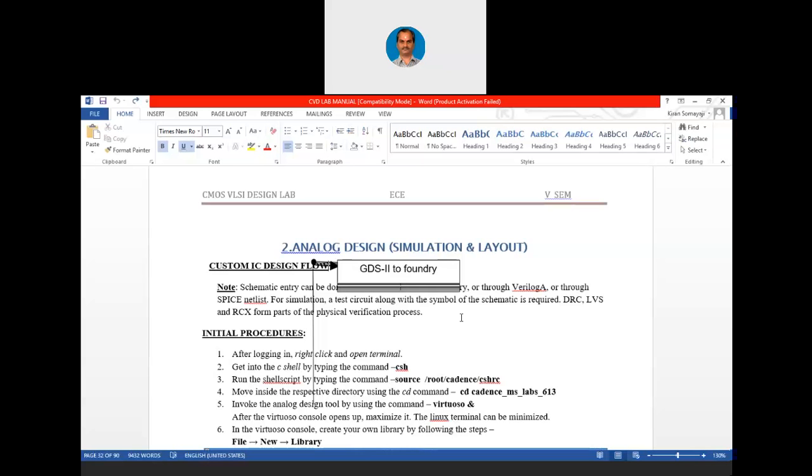The reason is we are not going to manufacture the complete test circuit diagram. We are going to manufacture only the main circuit diagram. For example, today you saw an inverter circuit, only Pmos and Nmos. We are going to get only the inverter manufactured. We are not going to apply the input signal and plot the output signal, that VDC and Vpulse, all those things we are not going to get manufactured at all.